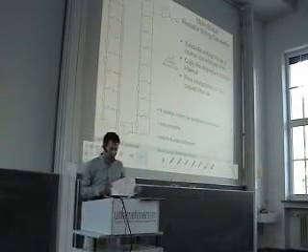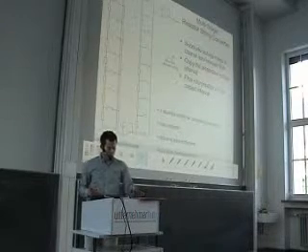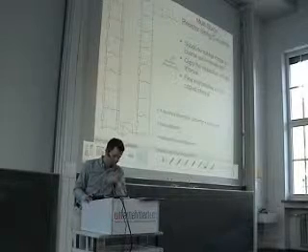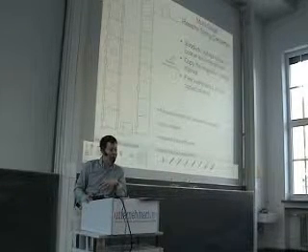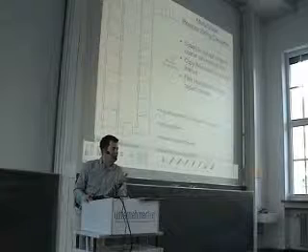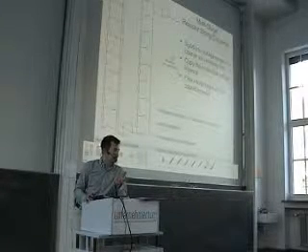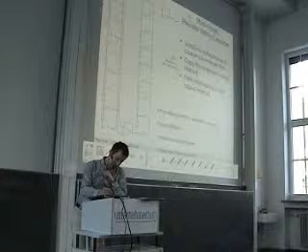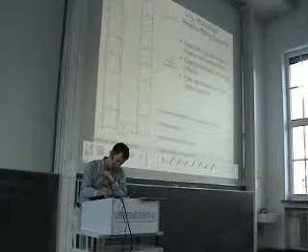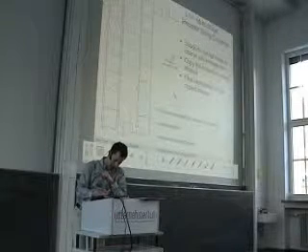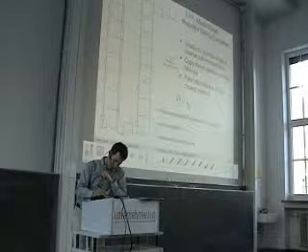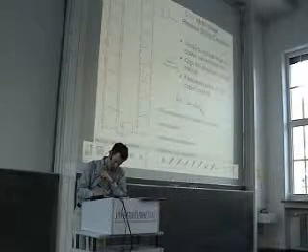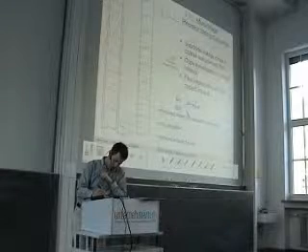This is an architecture that can be used to reduce the effort if the number of bits increases. So you know, if the number of bits increases, then I need 2 to the power of n switches and 2 to the power of n resistors. So if we think about a 6-bit structure, this would require 64 switches and would require 64 resistors.